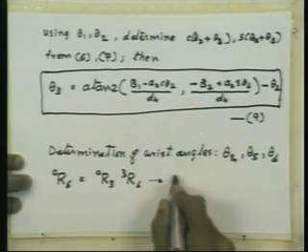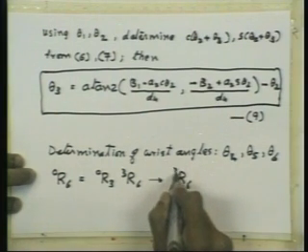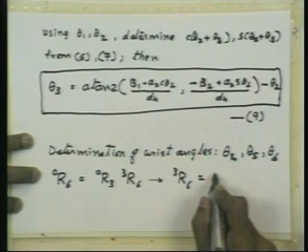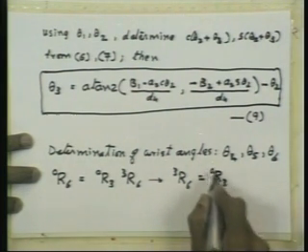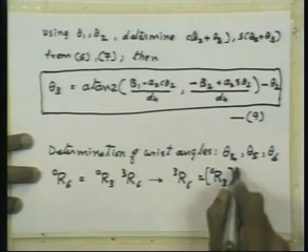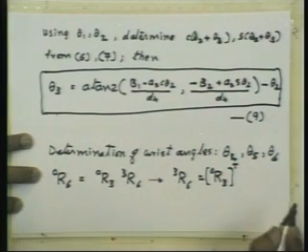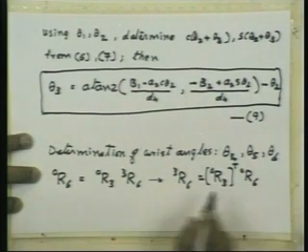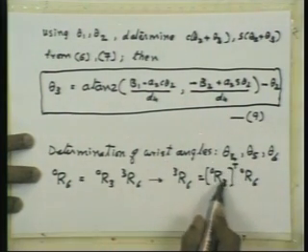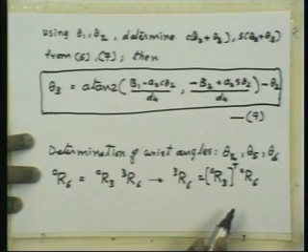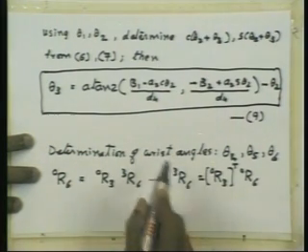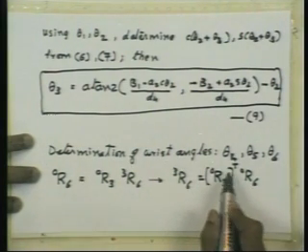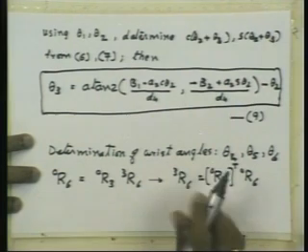So then R6 with respect to 3 can be obtained numerically, okay, as R3 with respect to 0, inverse of that, which is the same as the transpose of that, into R6 with respect to 0. You will see that this transpose is nothing but R0 with respect to 3. That is how this becomes R6 with respect to 3. Okay. So what we have here is that we have the right hand side numerically, we have this matrix numerically.